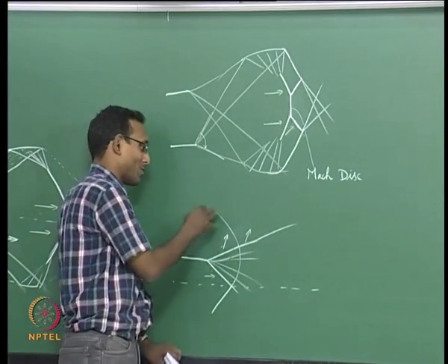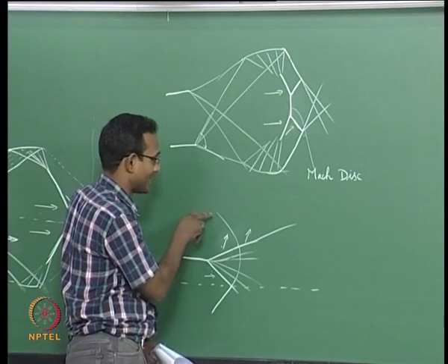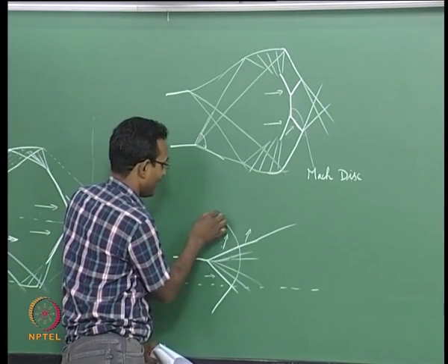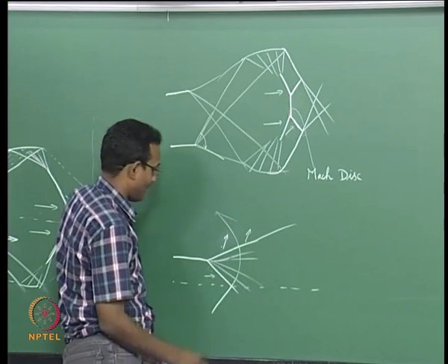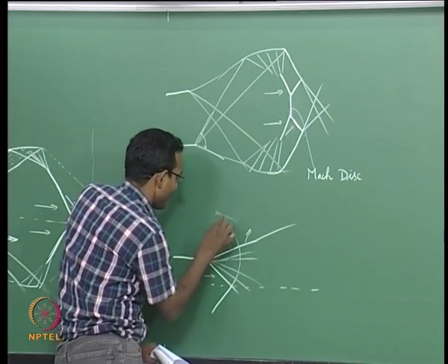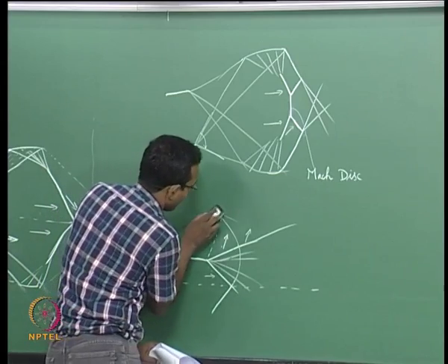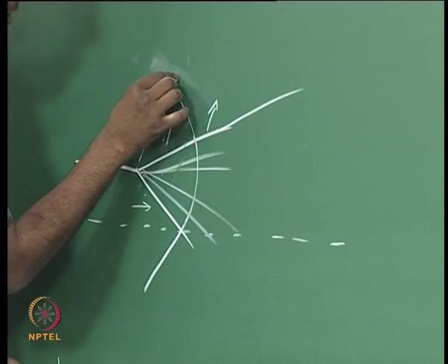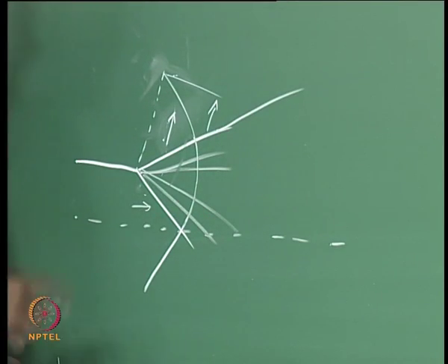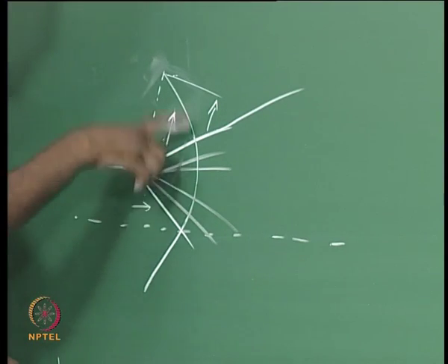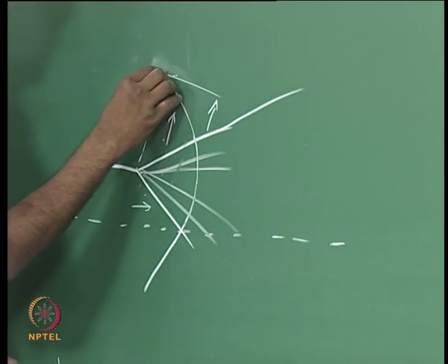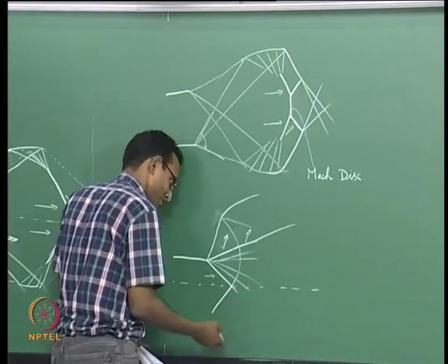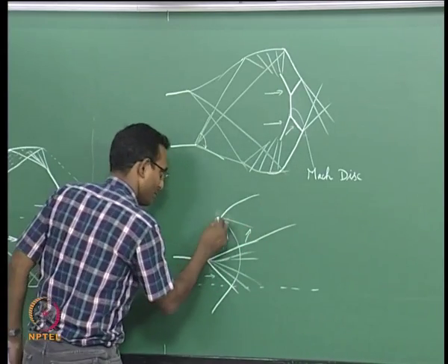Okay. Then you will have more complex phenomena happening here when this expansion goes and hits there and tells that it has to become a compression wave. Okay. Typically it is going to hit and come back as a compression wave from there. There will be a whole bunch of compression waves coming. If I think about this as my jet boundary, then it goes and hits there, and then from here there will be a compression wave coming back. Till here it is a straight line. This is my first wave I said. Every other wave is also going to go hit and come back. So, my jet boundary becomes something like this. I will use some other color for jet boundary. Let us say I use this whatever orange color for this.